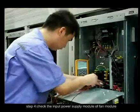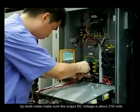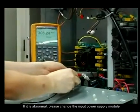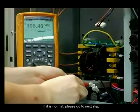Step 4. Check the input power supply module of the fan module with a multimeter. Make sure the output DC voltage is about 310 volts. If it is abnormal, please change the input power supply module. If it is normal, please go to the next step.